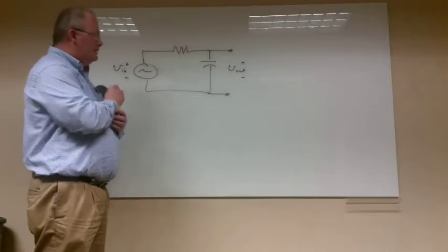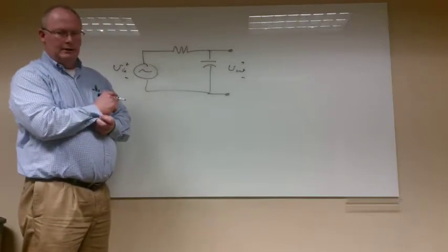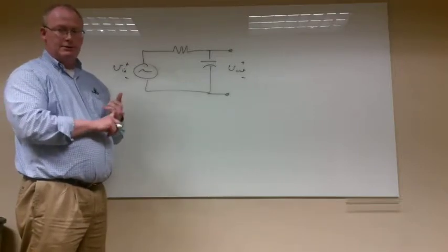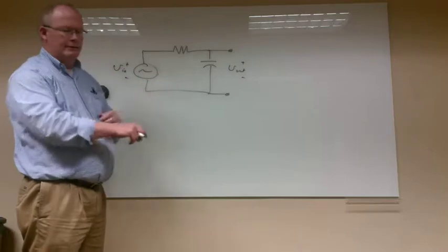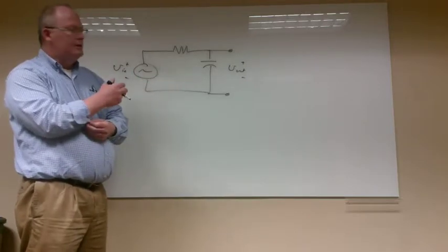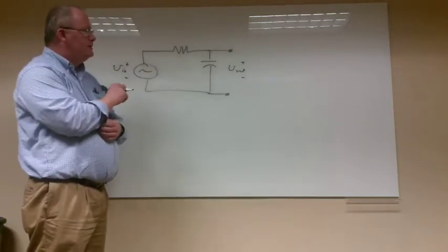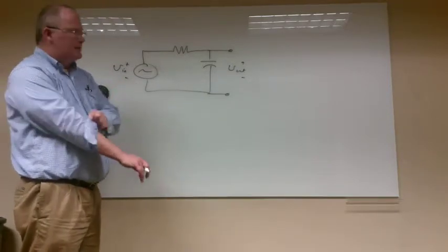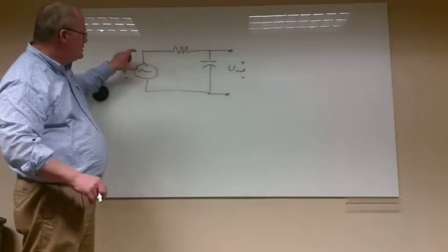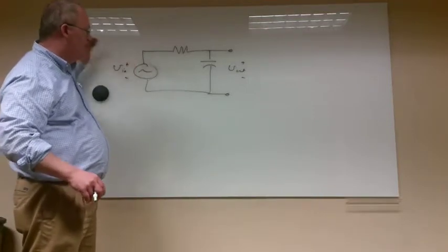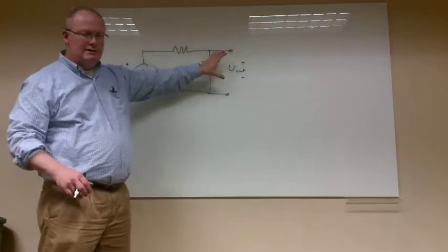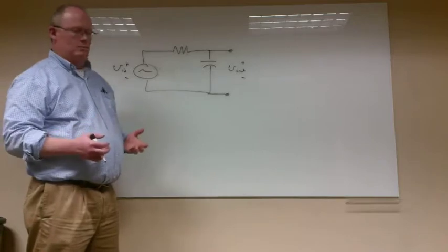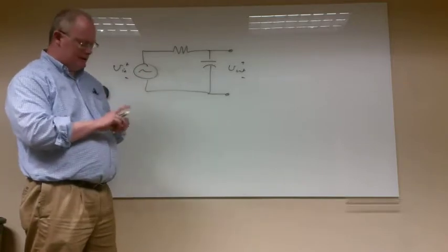Well, this is the heart of what you were doing. The op amps were utilized so that you wouldn't load your function generator by trying to push too much current through the RC circuit. And in addition, if you directly measure the output voltage here, that might load the capacitor. You would have had a different measurement there. And so, again, you actually used a voltage follower to provide this voltage from the function generator. And over here, you did have a voltage follower that you were measuring this output voltage with. But the heart of it all is still an RC circuit like this.